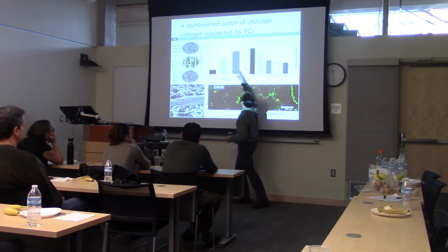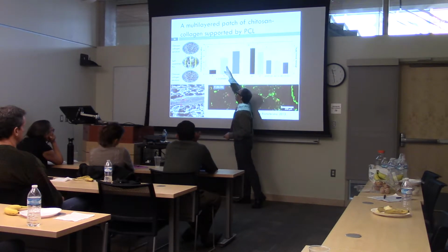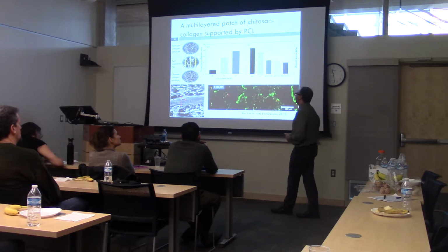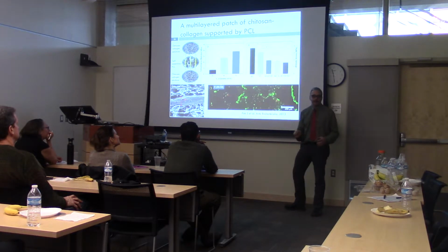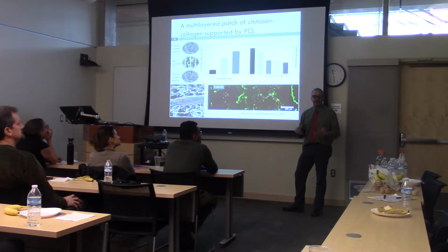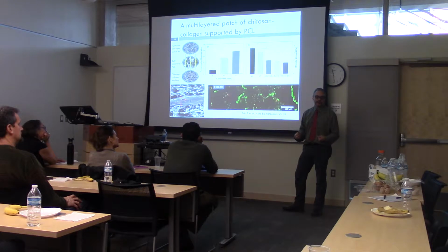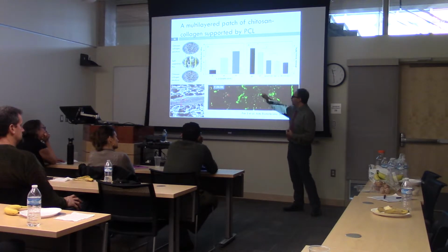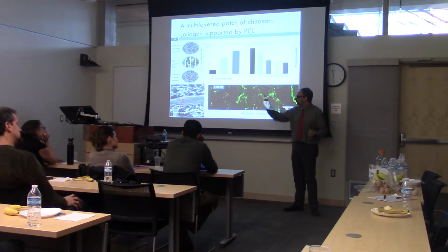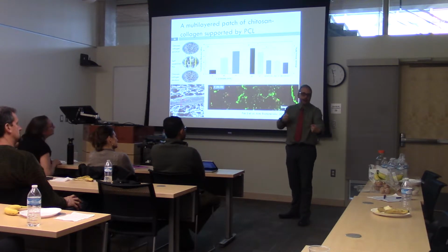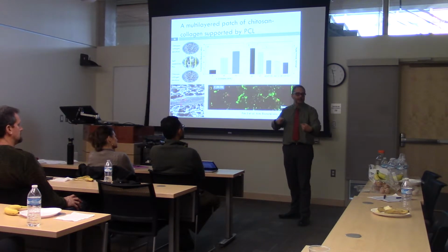And we get compressive modulus by varying the amount of gelatin, where we can tune the compressive modulus to between 10 and 15 kilopascals, about the number that matches the compressive modulus of native heart tissue, while still maintaining an ultimate tensile stress where these will withstand ventricular pressures and a suture strength. And what's great about the way that we were making it, it's really the polycaprolactone that's putting in the suture strength, we could suture it to a pig heart and then pull on it, and the suture actually pulls out of the heart muscle from the pig heart.